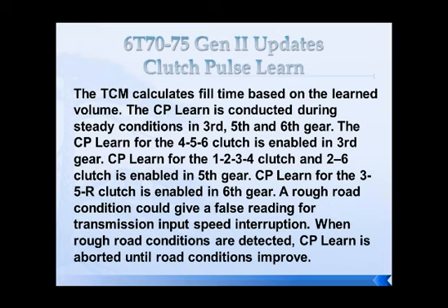Now the kicker with this is you will get customers who come in and comment about this. We've had several shops that said they've had to educate their customers already on it. So bottom line is going to be that this is considered a normal condition. About every 1,000, 1,200 miles, it's going to go through and try to relearn those clutches. Now it's going to relearn some others earlier and some others later than that 1,200 miles. And that's all based strictly upon how often you actually use the clutch. So the more often the clutch is cycled on and off, the more often we have to learn it.